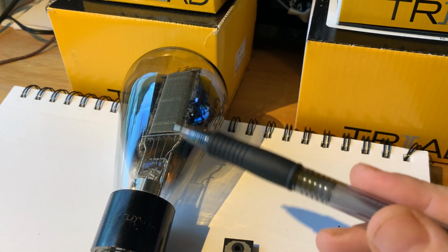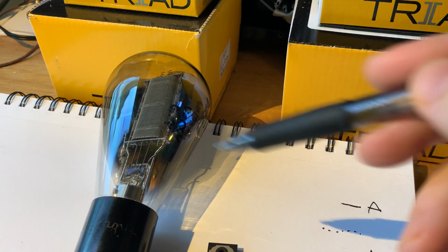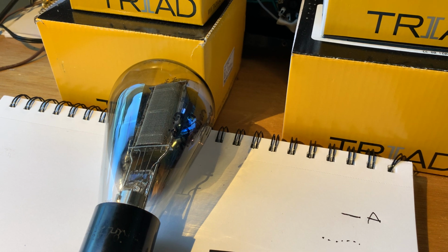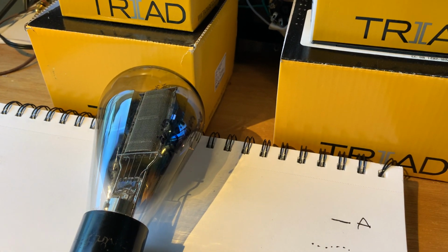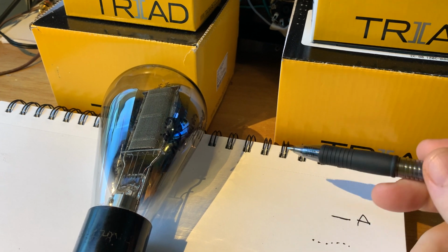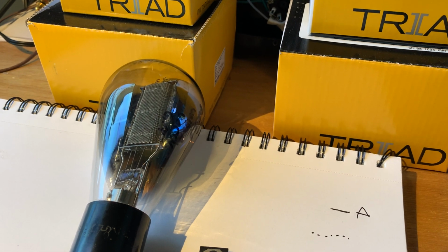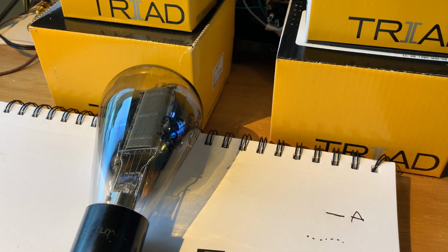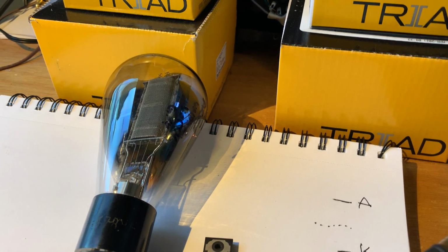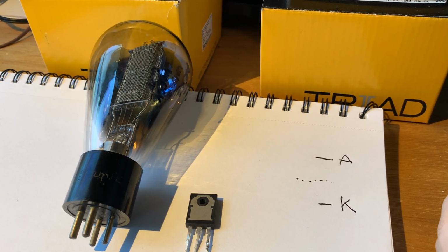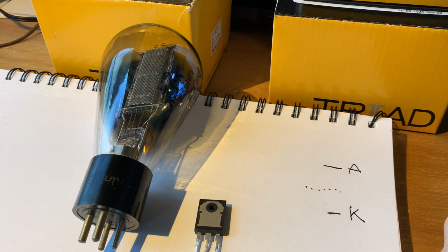What they used to do in broadcast is submerge the vacuum tubes in a liquid bath and circulate that fluid, and the fluid conducts away the heat, and that can act as a tremendously strong heat sink. If you don't want to go to those extremes, you can blow air on the glass and cool the tube tremendously. But you can also add simple heat sinks, which is basically pieces of copper surrounding the bulb, and blow air at it, and then the heat transfer will be much better, because copper is much better at transferring heat than the glass is. Anyway, for both of these devices, when they operate, they generate a lot of heat, and if you heat sink them, one, they can attain much greater power, and two, they live much longer.